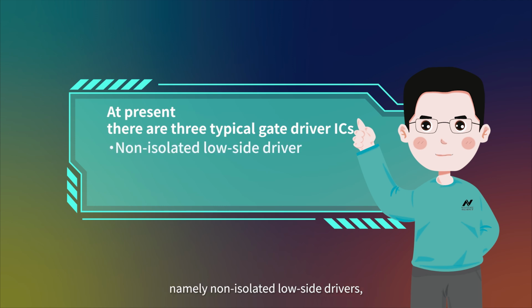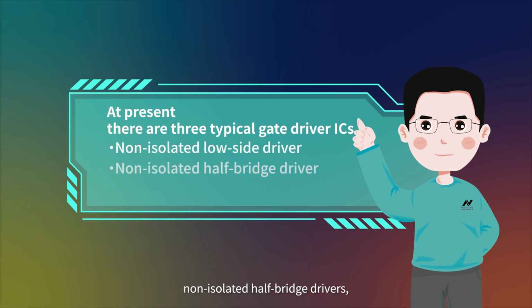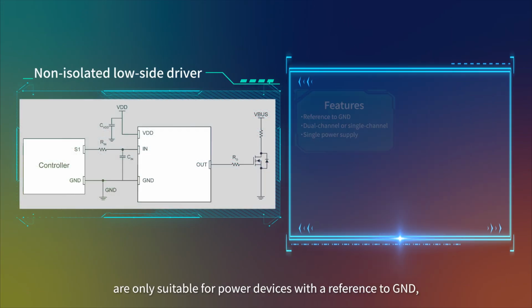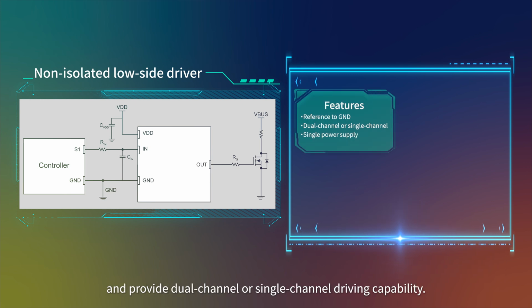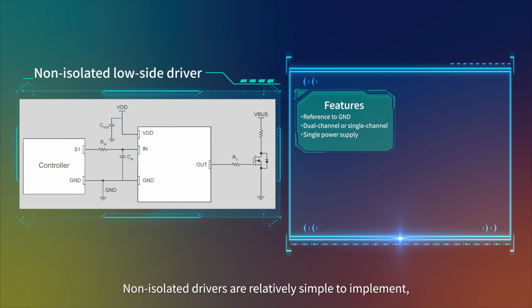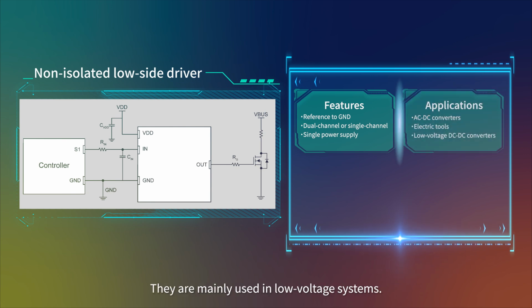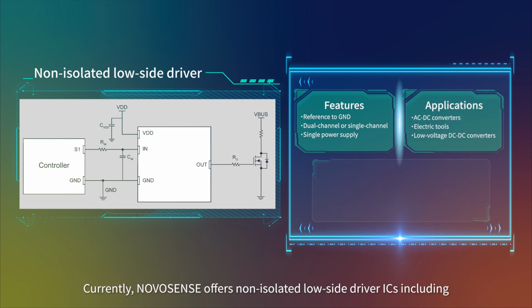namely non-isolated low-side drivers, non-isolated half-bridge drivers, and isolated drivers. Non-isolated low-side drivers are only suitable for power devices with reference to GND and provide dual-channel or single-channel driving capability. Non-isolated drivers are relatively simple to implement, requiring only single power supply. They are mainly used in low-voltage systems.